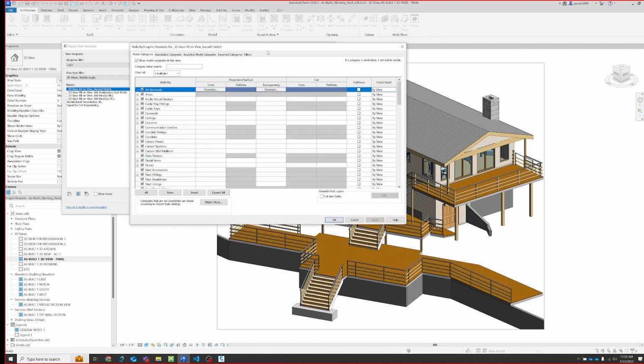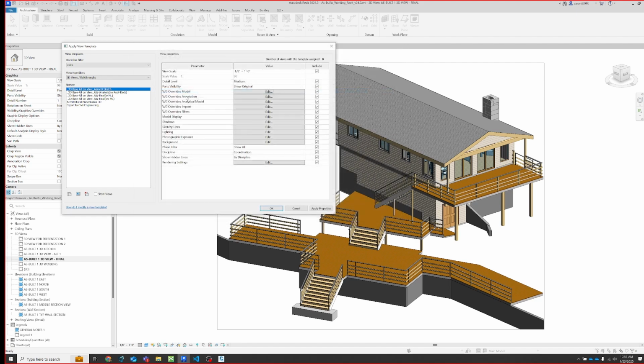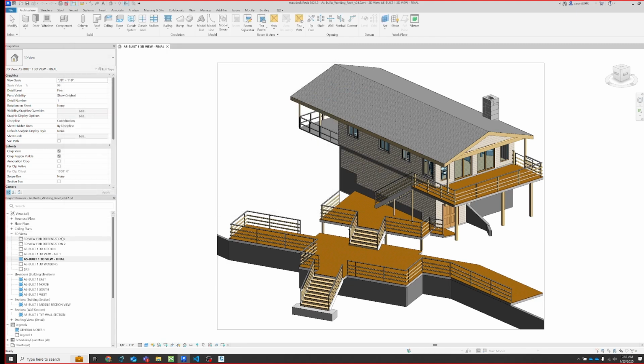You can go into any aspect of the model, and you can give it different shadings. You can turn it on and off completely, an entire category, say like all walls or all ceilings or all model lines. You can get pretty deep in here, but you can edit these after the fact is what I'm trying to say. But I've made a couple already.